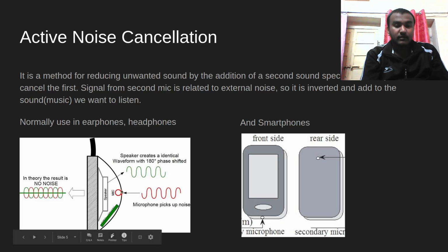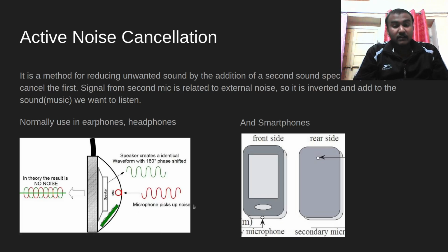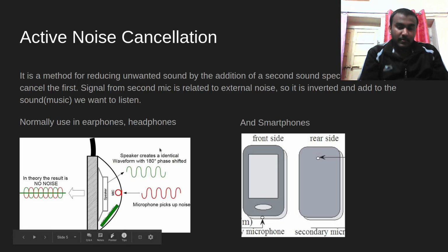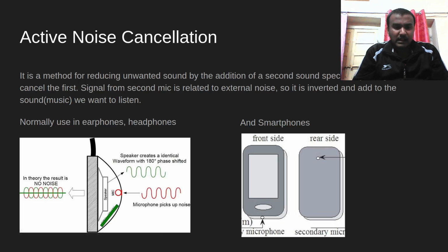of the headphone has a mic which can capture the noise that is created outside and create a 180 degree phase shifted form of it, and it can play that 180 degree phase shifted noise through the speakers. So when the 180 degree phase shifted wave and the noise meet each other in our ear, we hear no sound.